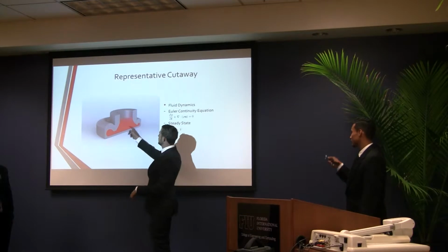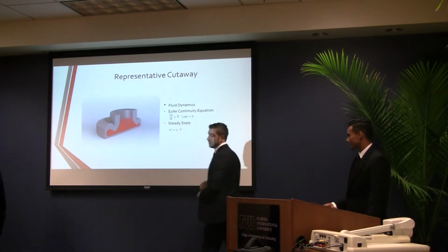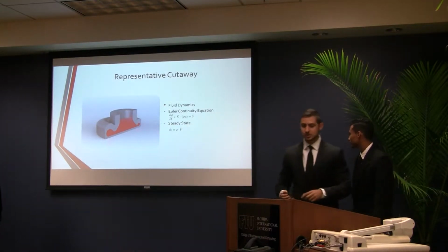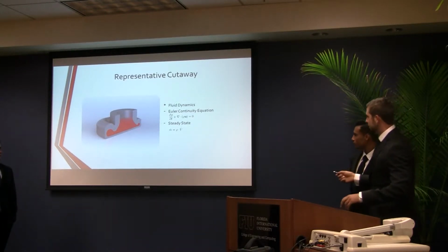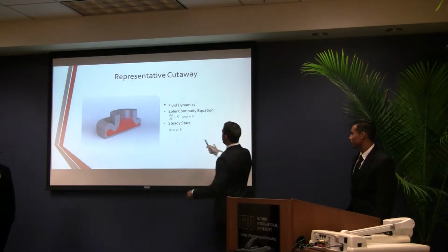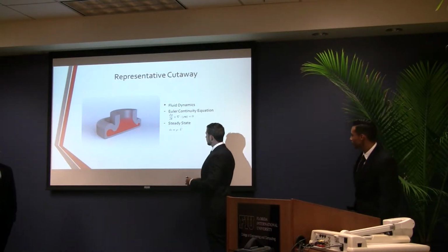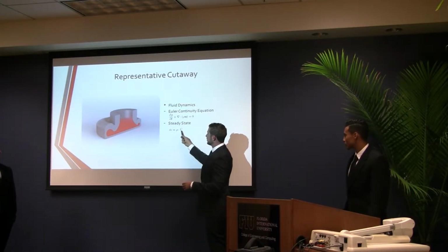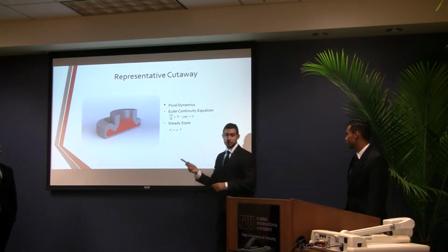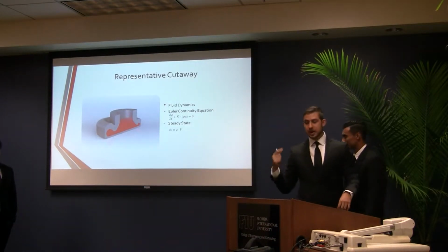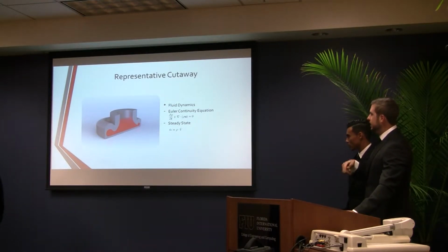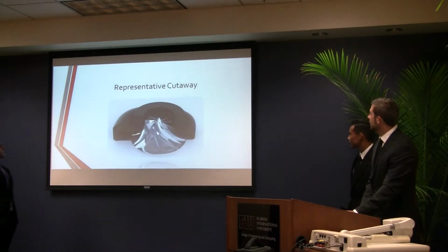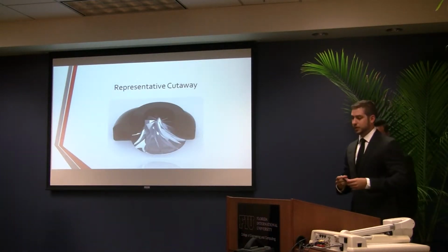So regarding fluid dynamics, we have the continuity equation from Euler, and here we can see that there is a difference in area at these 2 points. The continuity equation says that every mass that gets into a system has to get out. So here we change the area. From here, in the steady state, we see that the mass flow rate is the velocity times the area. So if we reduce the area, we're going to have higher speed. But if we increase the area, we're going to decrease the speed, increasing the pressure, because when the velocities drop, we increase the pressure.